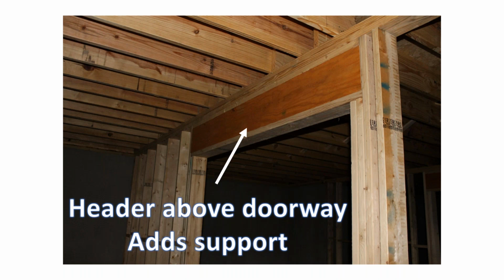And if you take out a wall that is underneath a supporting beam, you are going to have a sag unless it's been engineered by somebody, and they've either put a header in to offset that load, or they've dropped a beam in the attic so that you can't see it, but something's got to be added to handle the load, and that's what this header is about. This is going to offset the load of all of these joists sitting over this opening, whereas you've got a stud every 16 inches holding up your weight over here. So when you've got a wide opening, they put a header in here, and then they shore it up on either side, no differently than a post underneath your main beam to offset that load.